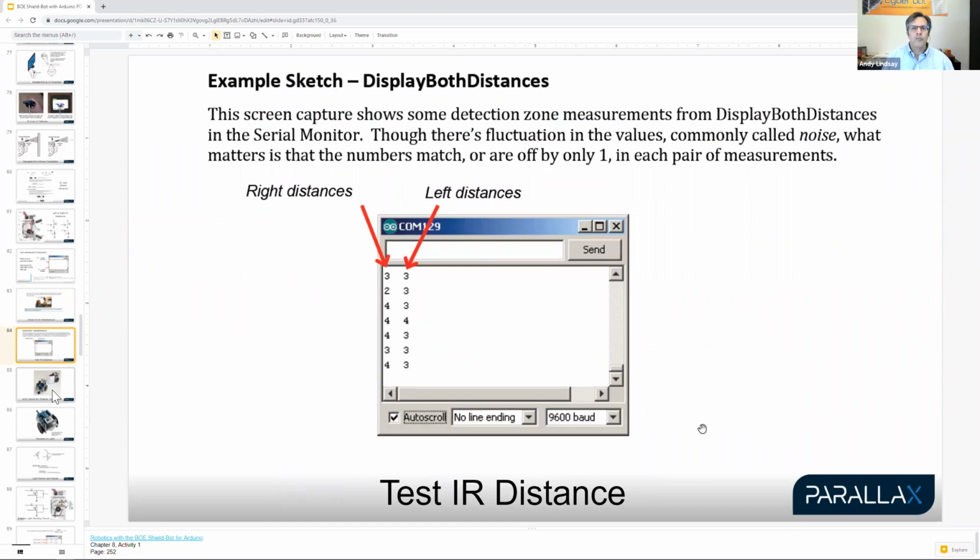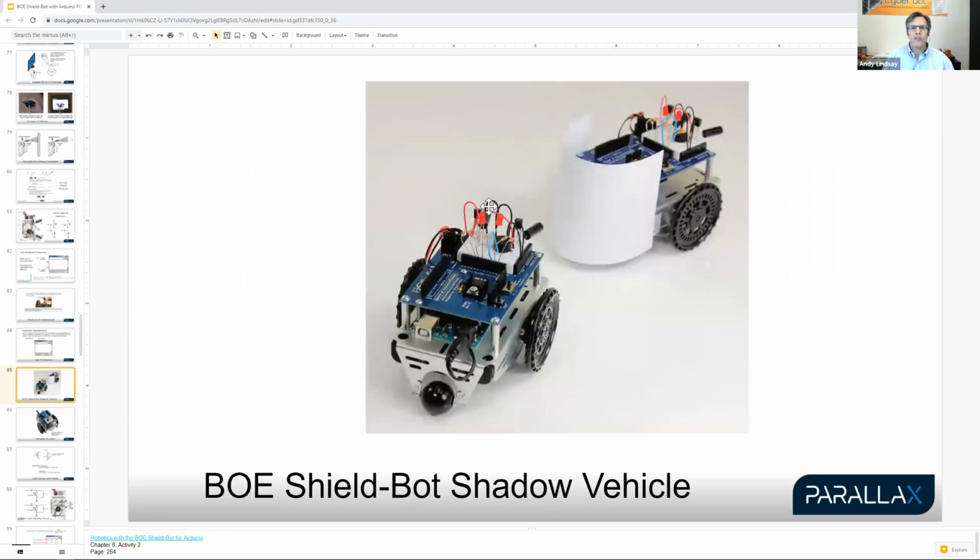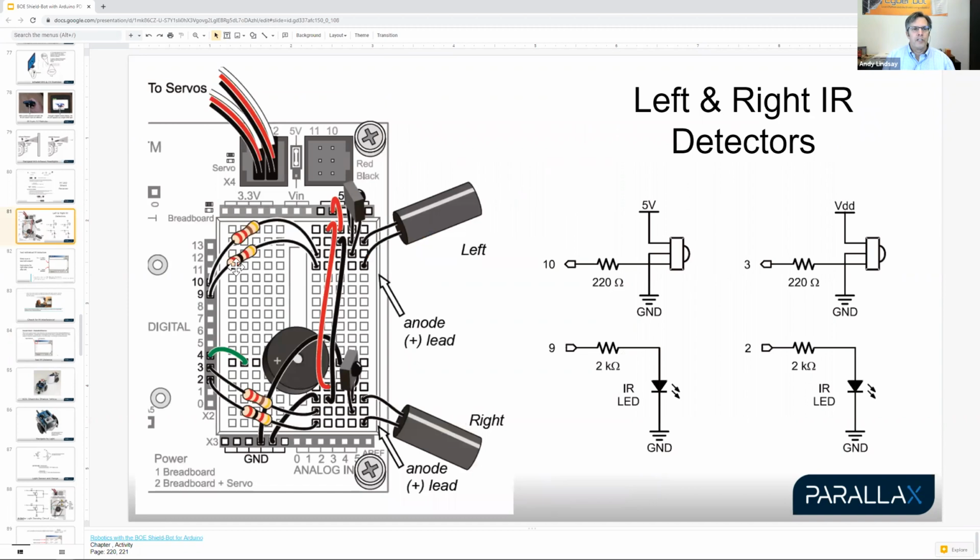It can avoid an obstacle without touching it, or it can even use distance and basic proportional control, for those of you who teach engineering, to maintain a distance between itself and an object in front of it, provided that you're very careful about using these red, black, red resistors connected to the LEDs. If you happen to swap these and use the red, red, brown, you'll have a much brighter light over here than over here. This will be super sensitive, and it won't follow very well.